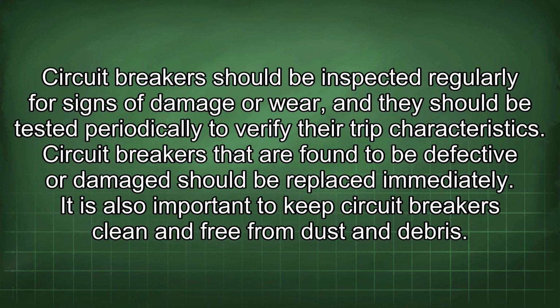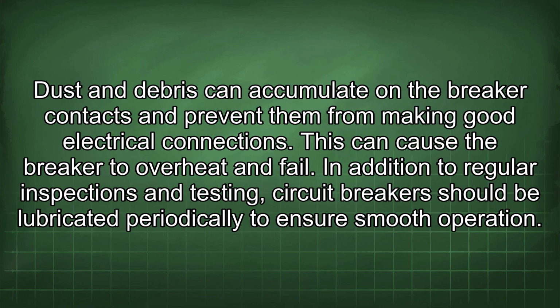Circuit breakers should be inspected regularly for signs of damage or wear, and they should be tested periodically to verify their trip characteristics. Circuit breakers that are found to be defective or damaged should be replaced immediately. It is also important to keep circuit breakers clean and free from dust and debris. Dust and debris can accumulate on the breaker contacts and prevent them from making good electrical connections. This can cause the breaker to overheat and fail.